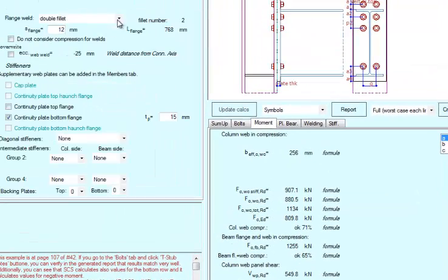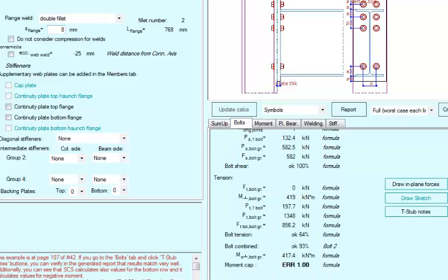This happens because we have loaded the file with final data, which differ from what the book uses in this calculation. The compression stiffener is not input in this phase, and the flange weld size is assumed to be 8 mm. If we change the weld value, we get the same result as the manual, that is 100% capacity. Shear force check also provides 100% capacity as expected. One seems to be okay and the other doesn't because of decimal rounding.